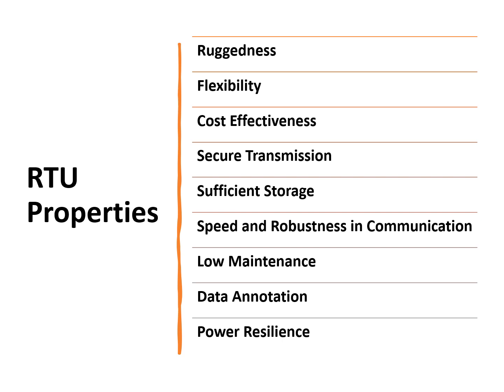Power resilience. An RTU must be supported by backup power to be able to remain in operating mode in cases of primary power failure. This can be accomplished by portable batteries or solar power.